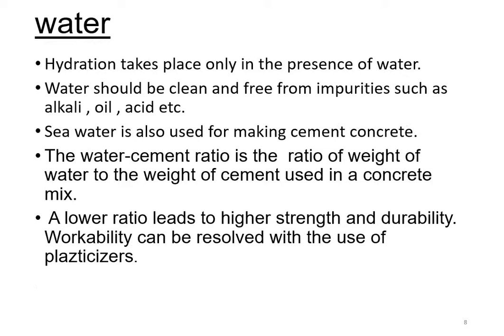And then you have water. Why do you have water? Only in the presence of water does the hydration of the cement particles take place. If you take the cement as such, it does not have any binding property. The moment you add water to the cement, what happens? The cement starts its hydration, an exothermic reaction, and then binds the aggregates, the fine aggregates and coarse aggregates together, and they form a hardened mass.